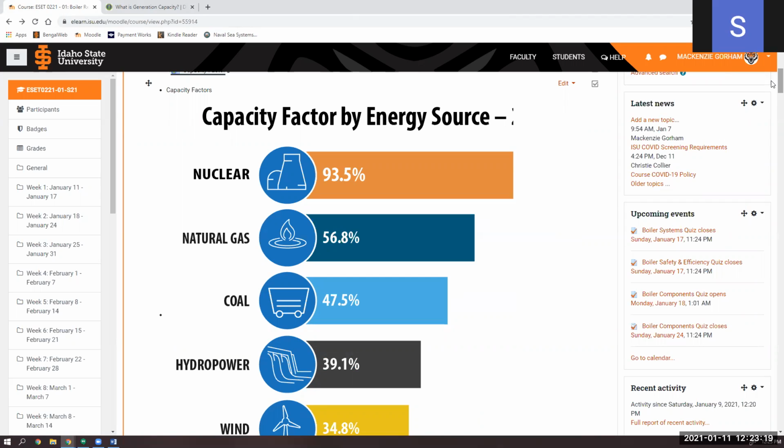Isn't the hydropower just because they're holding water back from the farmers and the dams? And also because hydropower, at different times of the year, you can have more or less production that you're actually able to make. So when they say that they can produce however many megawatts, say you've got a plant that can produce 500 megawatts, well, maybe it can produce 500 in the spring, but it can only produce 400 in the fall. So even if it was producing all 400 all fall, that still affects capacity factor, right?